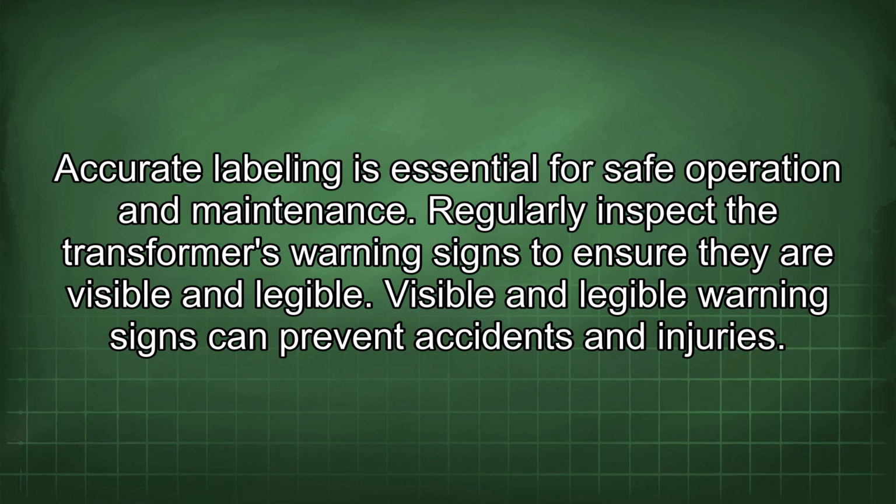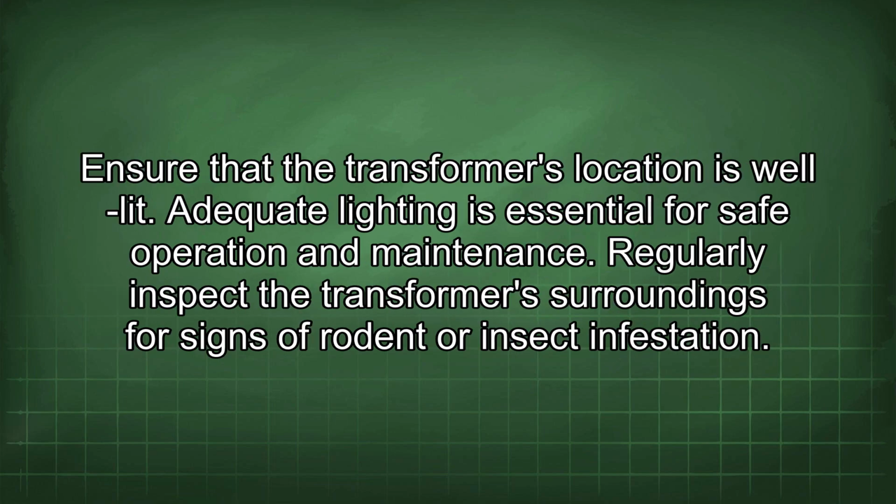Visible and legible warning signs can prevent accidents and injuries. Ensure that the transformer's location is well lit. Adequate lighting is essential for safe operation and maintenance. Regularly inspect the transformer surroundings for signs of rodent or insect infestation.